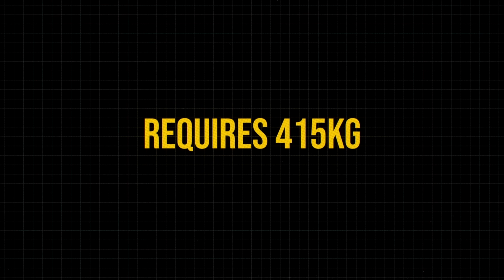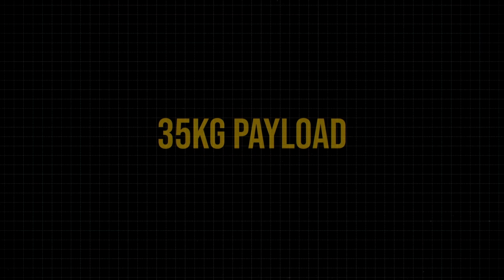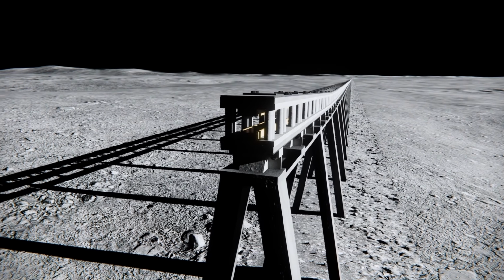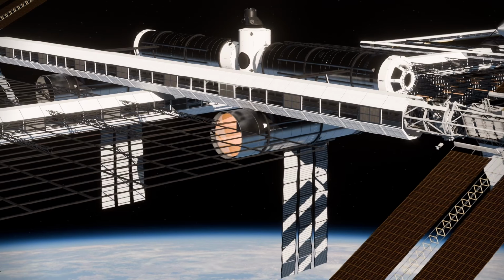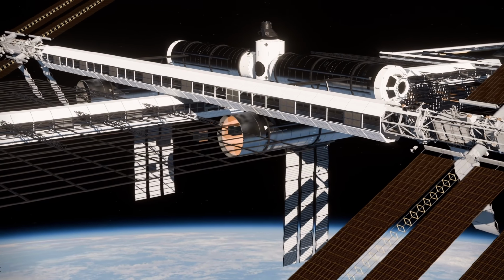But anyways, at 500 kilograms of wet mass, 83% propellant means we need about 415 kilograms of propellant, and that leaves about 85 kilograms for everything else. If we allocate roughly 50 kilograms to dry pod hardware, then about 35 kilograms remain for payload. That sounds small, but 35 kilograms every 3 minutes is still 700 kilograms per hour, or about 16.8 tons per day. And recall that the rocket pod itself is usable mass, not just its dedicated payload fraction.